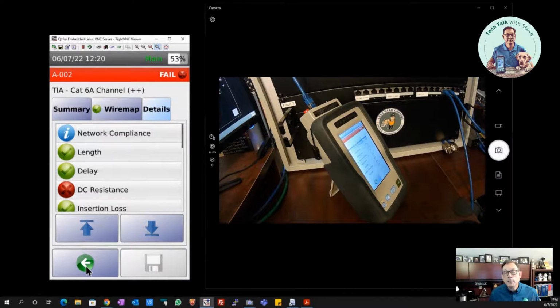What resistance can do, you could take a multimeter, and my brother-in-law has a friend, and he was helping her troubleshoot her boat. She had a battery in the boat, and she measured the battery. It was getting correct voltage, but she couldn't get the boat to start. So what happened is they figured out there was high resistance between that starter and the battery. And once you've got that high resistance, you couldn't deliver that voltage to the starter to actually crank the motor on the boat. So that's just a basic, simple example of what that resistance can do. And of course, with PoE, we start to see all kinds of other issues. So that's why that resistance is important.